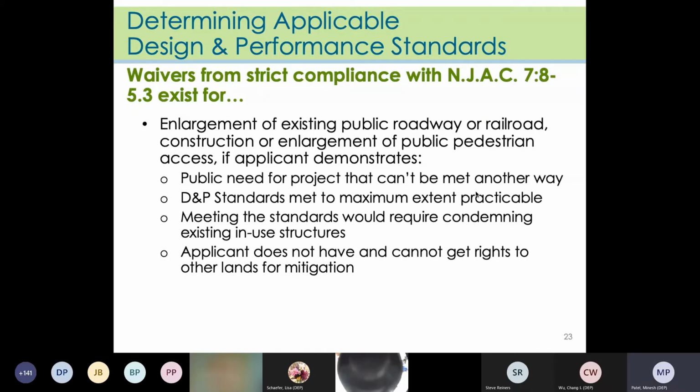Finally, the reviewer may also allow waivers to be granted for the enlargement of a road or a railroad, or the construction or enlargement of a public pedestrian access if the requirements here are met. They are as follows: public need for a project that can't be met another way, design and performance standards met to the maximum extent practicable. Meeting these standards would require condemning existing in-use structures, where the applicant does not have and cannot get rights to other lands for mitigation.